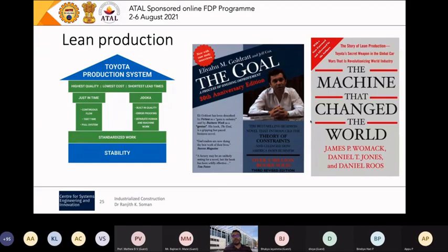They categorized every work into three categories. The first was value adding work, which means placing a part in a car, where there is a final value for the customers. Then there is non-value adding but necessary tasks, like taking the engine from the warehouse to the assembly line. That's not value adding for the customer, but it is a necessary task. Then there were non-value adding tasks, meaning rework, or placing something in the wrong place and then having to remove and replace it. And they went through the whole manufacturing line, looking at these values.